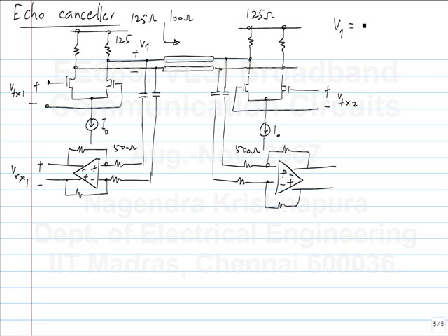No, okay, I0 is given as how much? 20 milliamps, right? So it is 20 milliamps times the total impedance connected to each side. How much is that? 50 ohms. Is it clear to everyone that it is 50 ohms that's connected? So you get 125 ohms and 500 ohms in parallel. The parallel combination is 100 ohms.